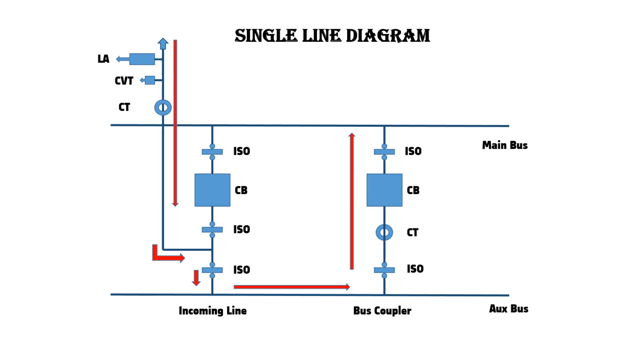For that, we need to transfer various signals from the distance protection relay. One is the single phase tripping, three phase tripping, as well as auto reclosing. Now this can be done in the conventional way through a lot of complex wiring, which needs a lot of time as well as a lot of material.